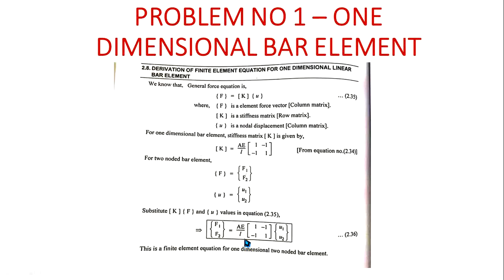Second, whenever there is a change in loading condition, whenever there is a load acting in between or at the end of the structure, at that specific point where the load acts you are supposed to provide a node, so that you have a division. I stress this point again, please remember, this is very important. Minimum you should have two elements; whenever there is a change in the cross section you have to specify an element, and whenever there is a load applied, you have to specify an element there.